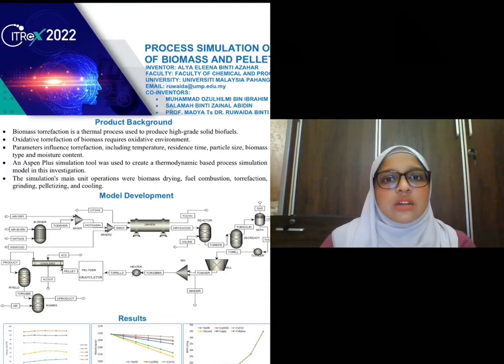Durability and bulk density of the pellet are the main factors affecting pelletization. For withstanding transportation, pellets have to be durable and strong. Durability of the pellet can be increased by increasing the moisture content of pelletization. Binders, which are organic or inorganic chemicals, can be introduced to biomass for pelletization in small amounts to enhance the mechanical properties of the pellet. Concentration of binder influences the pellet density, mechanical strength, moisture content, and also pellet durability.